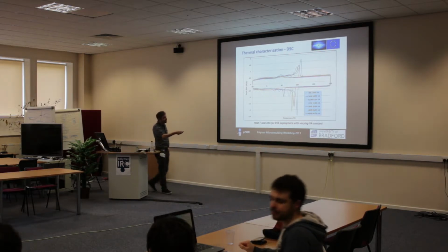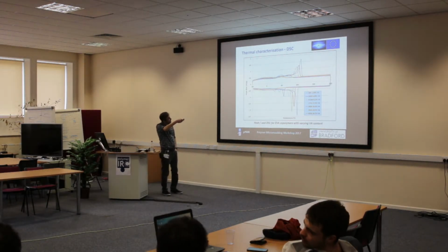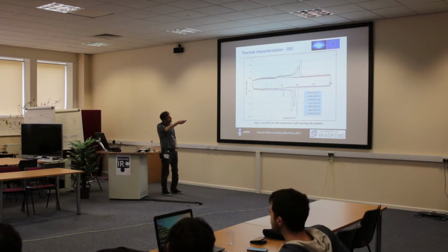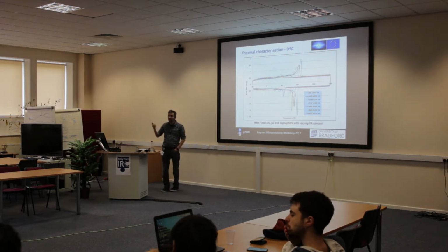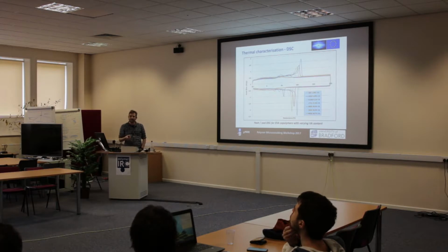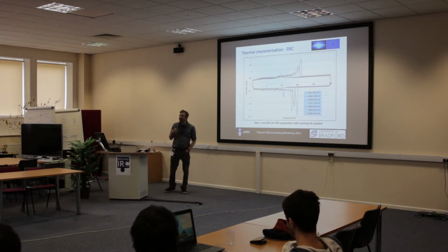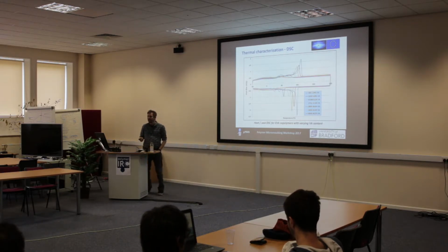So this vinyl acetate content, what you can see is here's our melting points. This is the lowest vinyl acetate, and slightly up, slightly up, slightly up. So basically by adding more vinyl acetate, we change the crystallization temperature massively. Why is that important in terms of process? It means that we don't need to put as much energy into our process to get it to work.